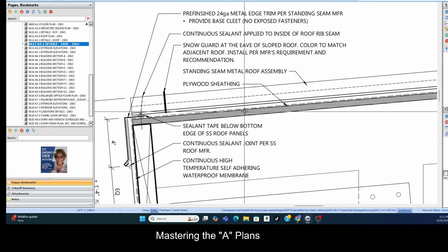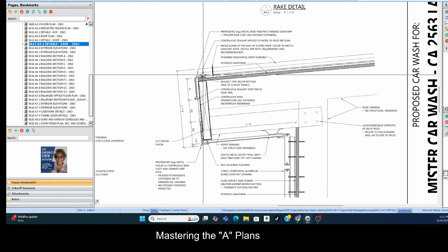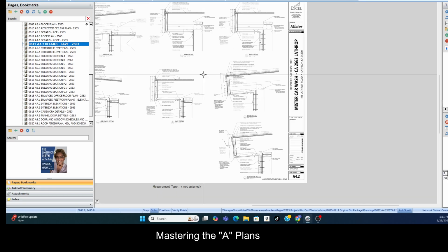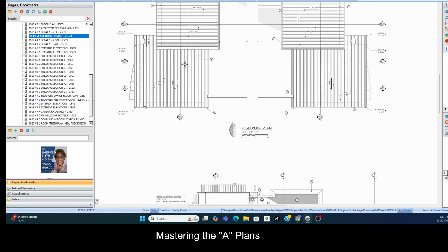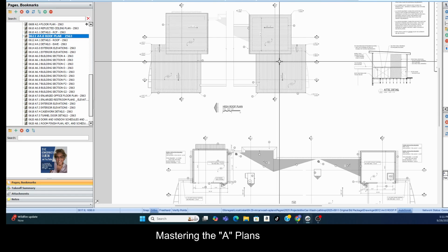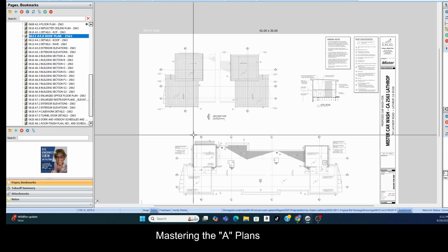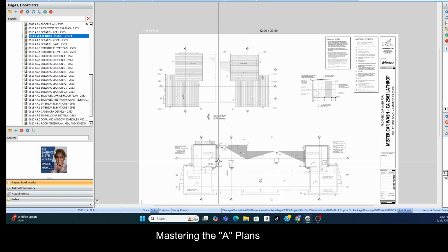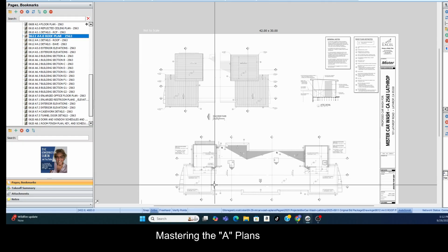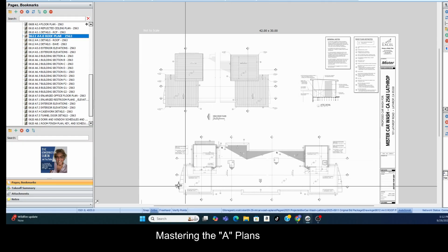Okay, the plywood, I'm the roofer. I'm not doing the plywood. I'm doing the roofing, everything associated with that roof and the sealants and all of that around all of the openings in the roof, all where wall to wall meet. Okay, so that's what the roof plan's all about. So let's go again. We have a high roof, and here's the high roof, and then the lower roof. And we have to make sure where wall to wall meet, that's leak proof, and where all the holes are.